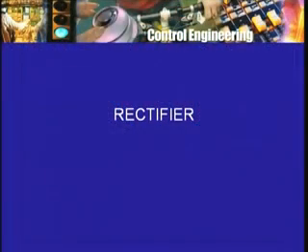Am I going to use an AC motor of what voltage, or I would use a DC motor? In that case I'll have to put a rectifier or a DC power supply for my DC motor if I have only AC supply available. Now that will cost some money and so on. So I'll have to look at those alternatives.